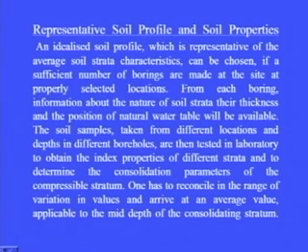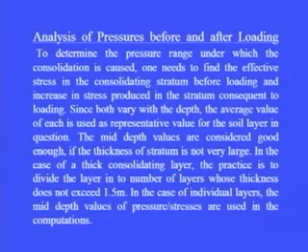The soil samples taken from different locations and depths in different boreholes are then tested in the laboratory to obtain the index properties of different strata and to determine consolidation parameters of the compressible stratum. One has to reconcile the range of variation in values and arrive at an average value applicable to the mid depth of the consolidating stratum.